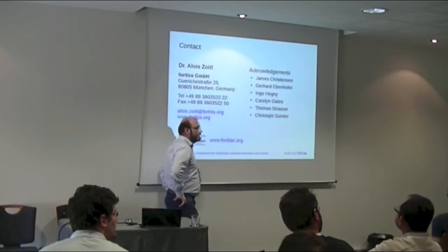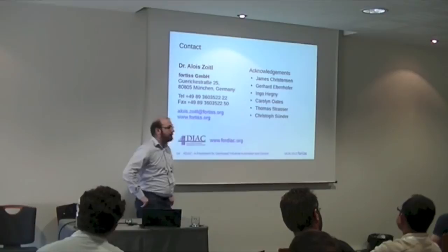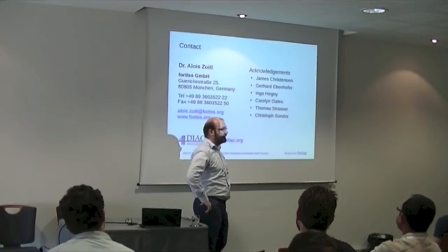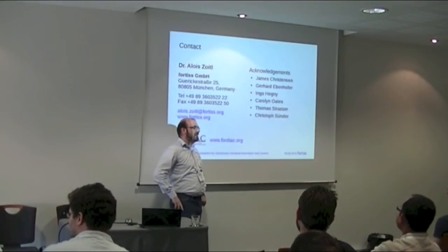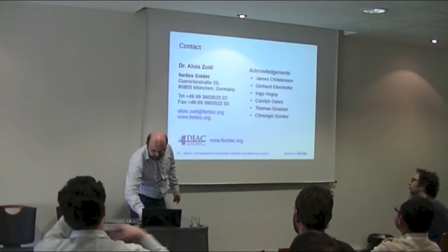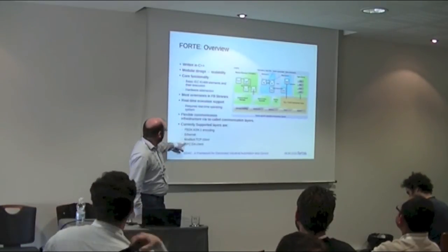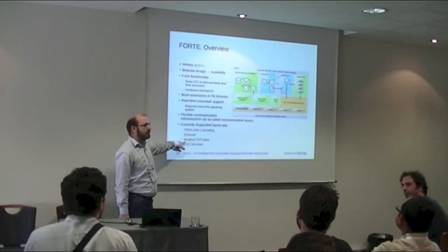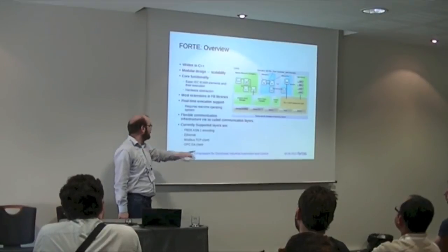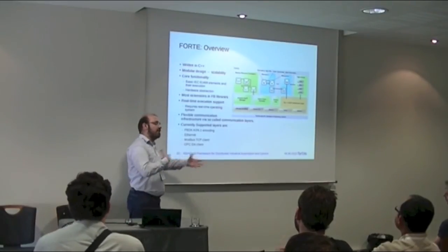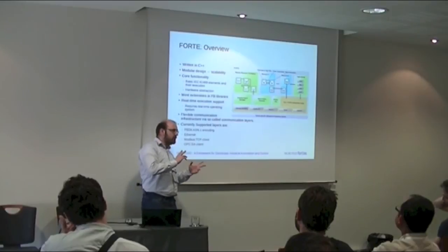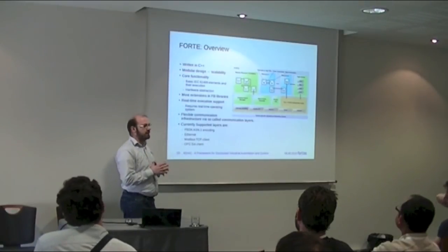What communication protocol do you use to establish communication between the functions deployed on the many devices? Currently we are using Ethernet, and either UDP or TCP, and on top of that an ASN.1 encoding, which is defined by the standard itself. But as I've shown here, we also have Modbus on the client, so you can have Modbus slave devices where you can acquire data. We have OPC there where you can acquire data, and if you need another protocol, it should be rather easy. It's about 1 or 2 classes, depending on the protocol, which you need to implement yourself.